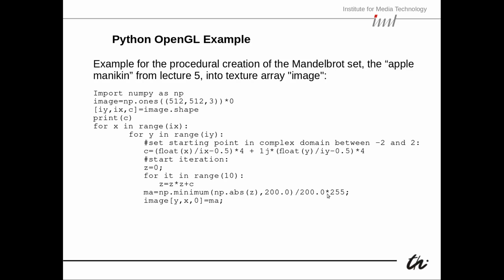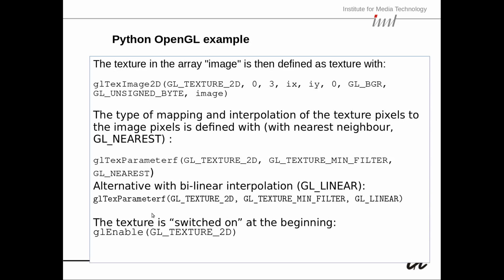Here I normalize it again and scale it to 255, so that it works like a color byte. And this is actually taken for primary color 0, which in this case is, I think, the red channel. So this should appear red. Yeah, so we have the choice of those two images, and then we can map them on our object,